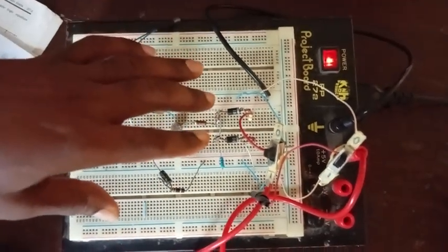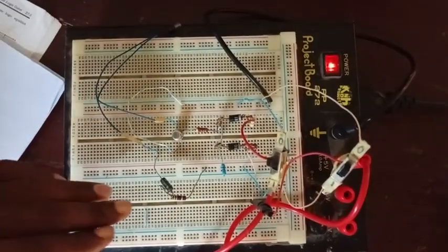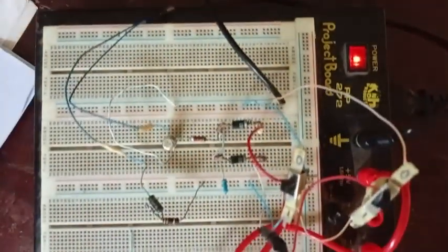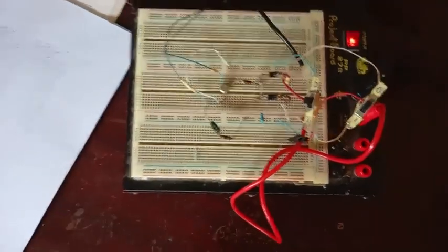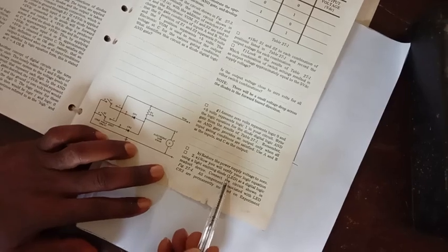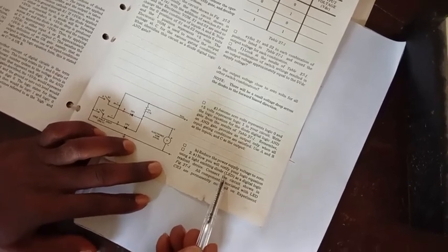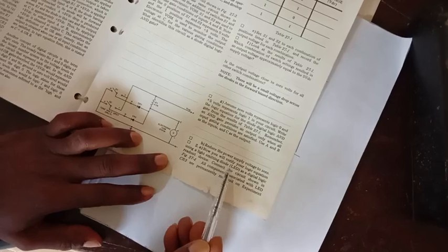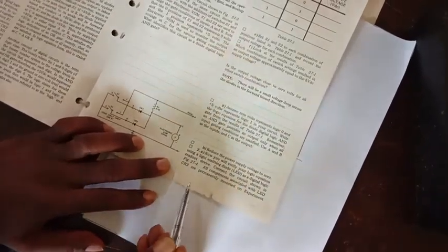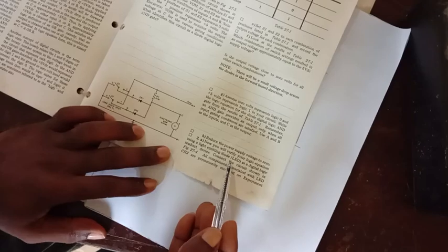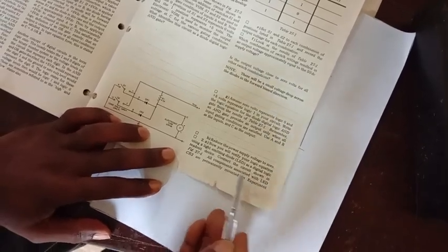We're going to use our 2 diodes. Then we use resistors and 2 switches, to control our inputs. Let's see what we're asked to do. They said now you will verify your logic equation using a light emitting diode. Though I use a miniature lamp instead of an LED because the LED can get burned. Though I can use a resistor so that it will not get burned, I have a miniature lamp to use instead of the LED, the same thing. So I put it at the output of the digital logic gate.